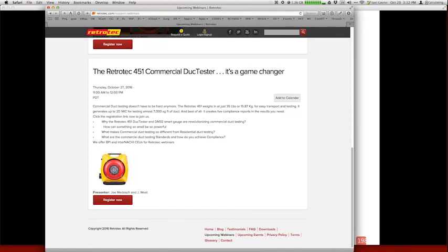Someone asked how do I change the volume or the area on the gauge from metric numbers. Excellent question. For those of you out there that have this challenge, I can help you with that. The DM32 gauge has units that are metric and what I call US standard on there. So it can go from meters to feet, or from feet to inches, or meters. So if you have area and volume that are showing up as metric, then tap on channel B,